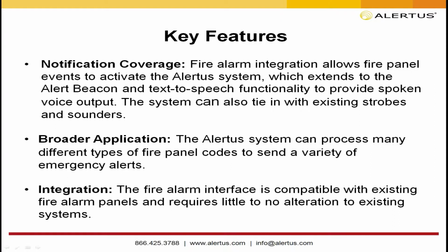Yeah, thank you, Ryan. First and foremost, as the code states, any strobe or any device that has been originally installed or used for the fire panel can be used by a mass notification system as long as neither that strobe or that speaker is labeled fire. If it is labeled alarm or not labeled at all, I've also seen alert, then it can be used for a mass notification system and can be leveraged as such.